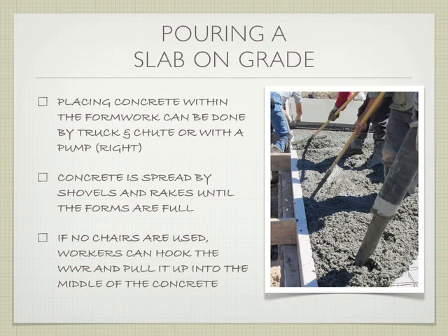The idea here is that you're going to pump the concrete from the truck into the formwork as close to its final resting place as possible. And chances are, when you're pouring it in, it's not going to be perfectly level. No matter how good you are at directing where that surging hose is going to go, it's not going to be perfect. So you need some way of getting the concrete to approximately the right level. You push as much concrete in as you can. After that, you use things like rakes and shovels to push it from one area up against a board that can help guide you. So you spread it with the shovels, you spread it with the rakes.